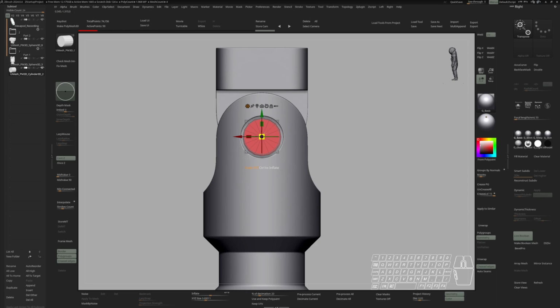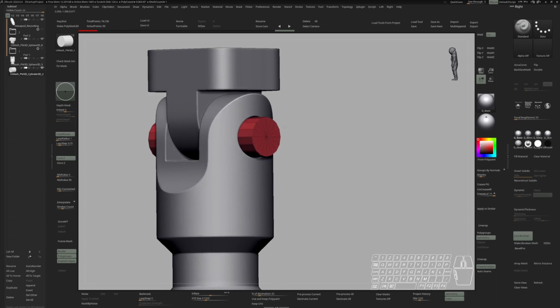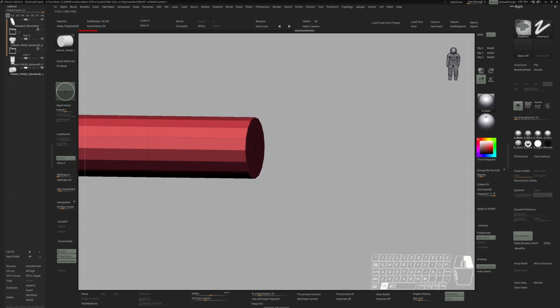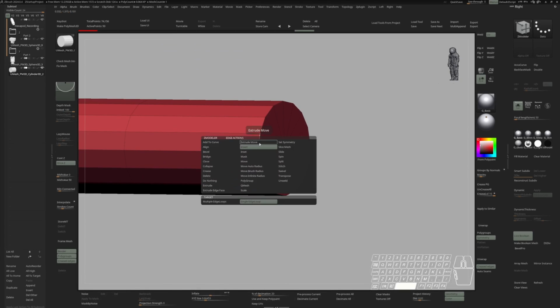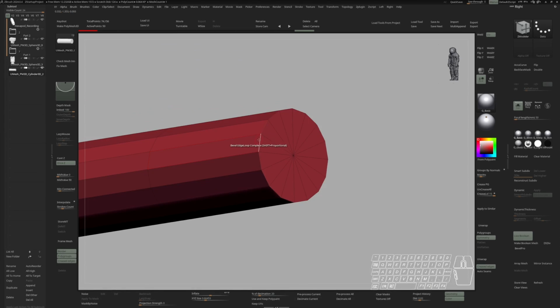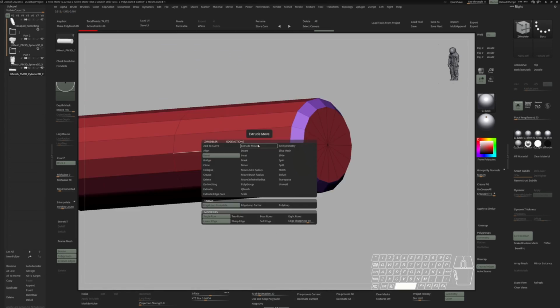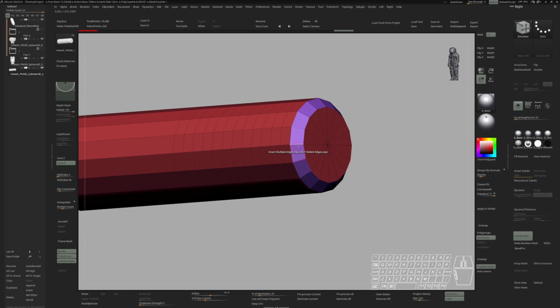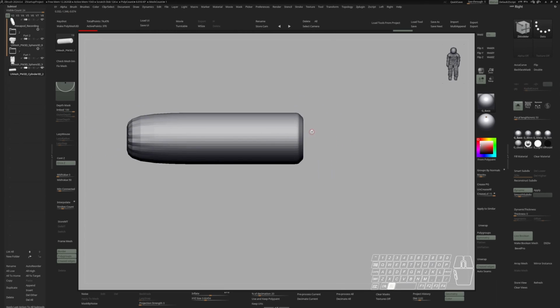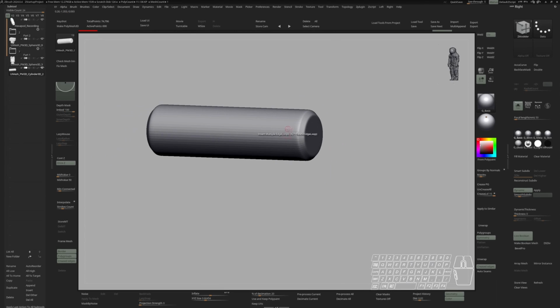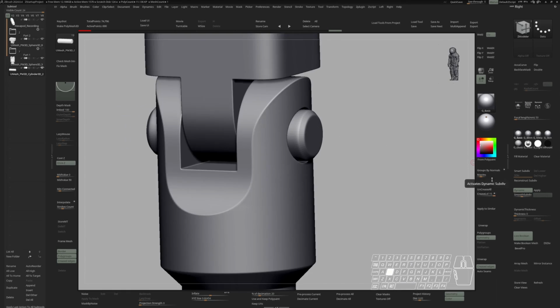Because our geometry got slightly destroyed by the Boolean operation, instead of using ZRemesher, I'm just using another primitive. I'm going to switch to my CurveModeler brush, hover over this edge loop, activate bevel, edge loop complete. Now I'm switching to insert, multiple edge loops, keep groups, give this some supporting edge loops. And hit dynamics. And also do a mirror and weld in the X axis. Let's turn up dynamics here.